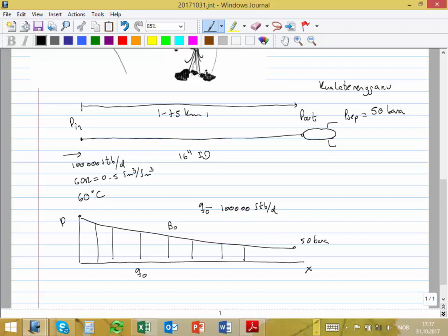So the way I suggest, I say split the pipe, and here we're going to make it in intervals. The delta X will be 10 kilometers, okay, 10,000 meters. But at home, for the home exercise, you're going to use delta X equal to 1,000 meters, okay, 1 kilometer. And you have to compare what is the effect of using a small step or using a big step.